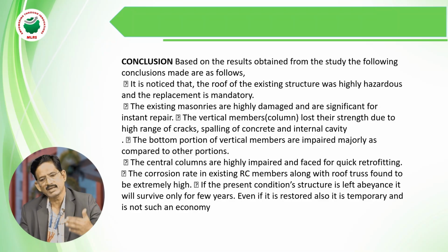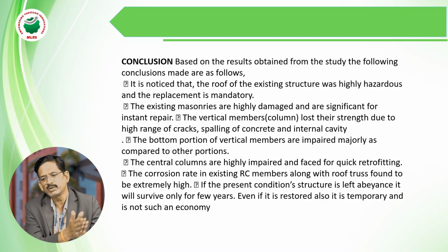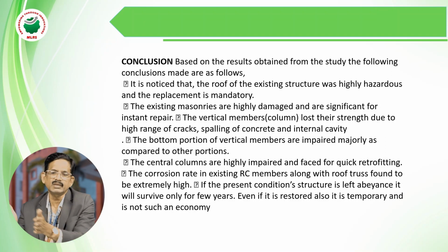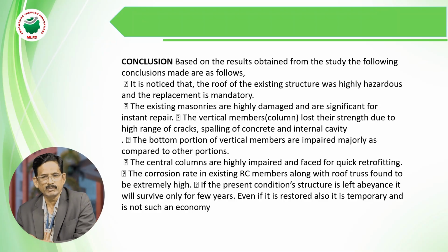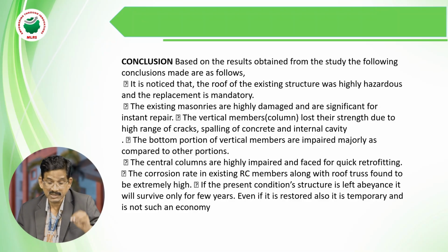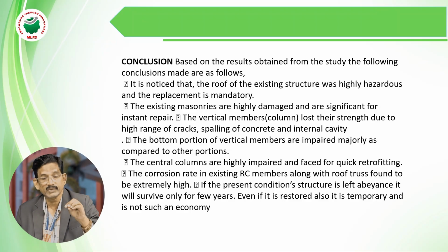After the final results, based on the permissible value and your actual value, you have to write the remarks, whether you have to replace the particular member, or repair the particular member, or do something else. So the existing masonry is highly damaged and assigned for instant repair. Immediate repair is required for the masonry walls.